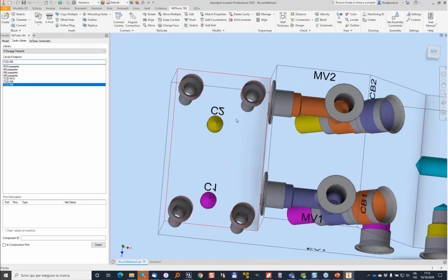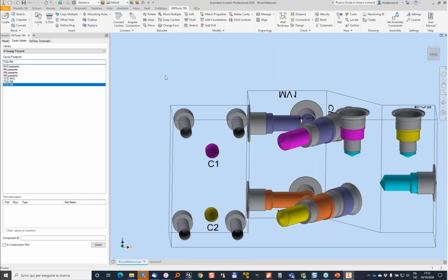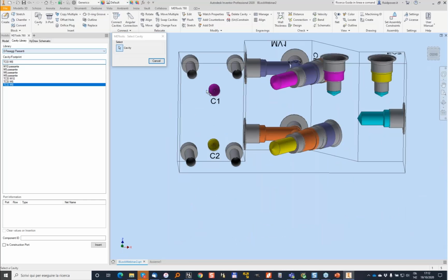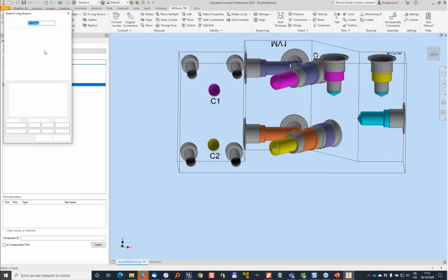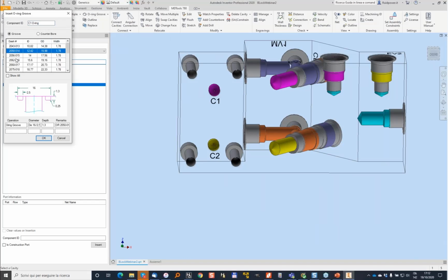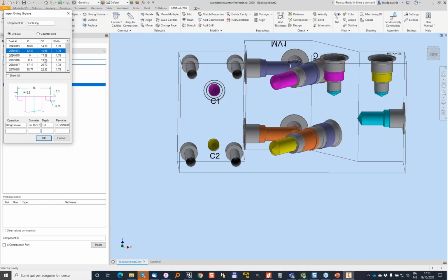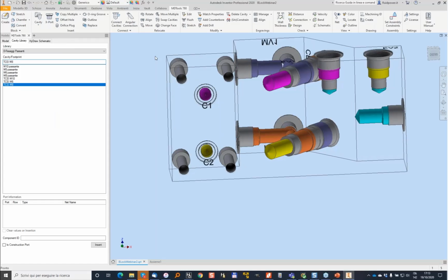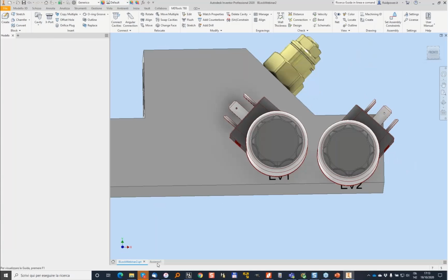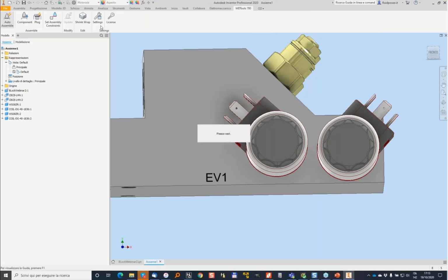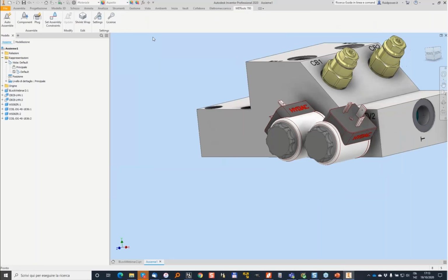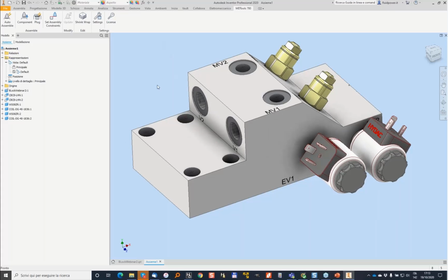Okay. Our cylinder will require some O-ring, so let us insert an O-ring groove on C1. And I take a series 2016 size. Okay, and the same here. Let me save again. Let us check again the assembly. Automatic assemble. Looks good. Let's conclude our block.